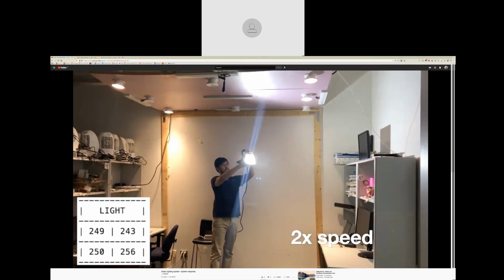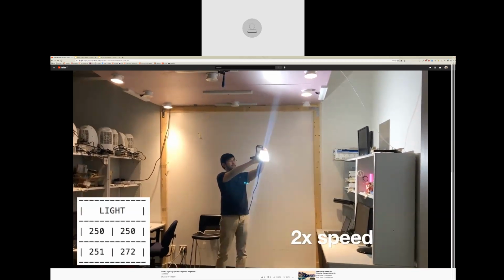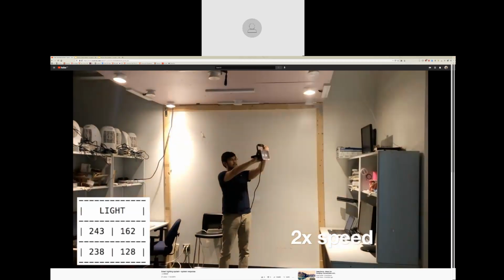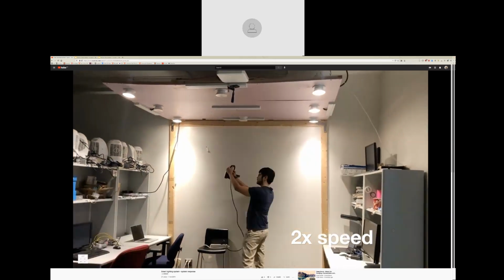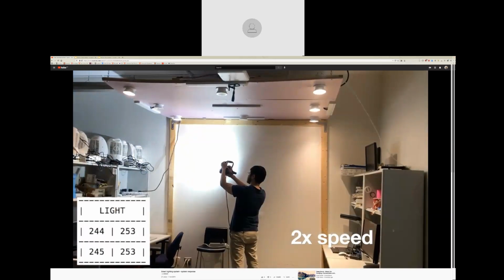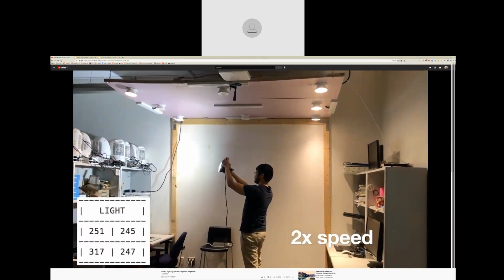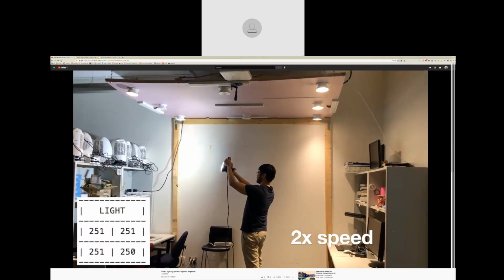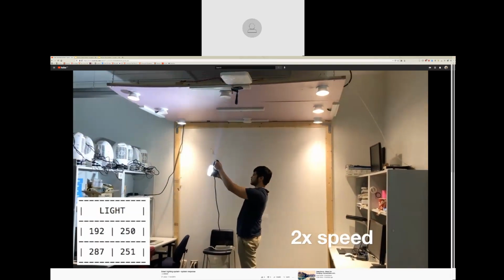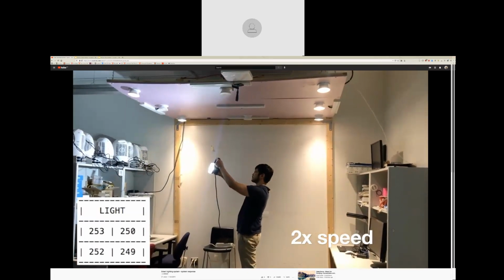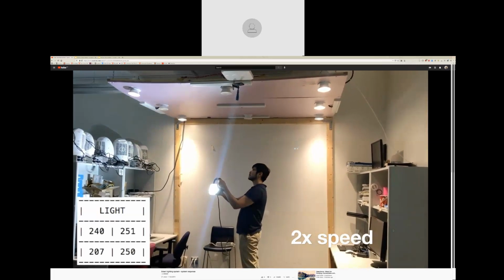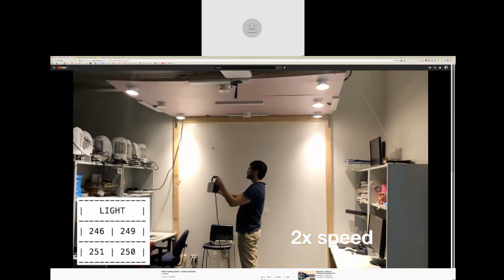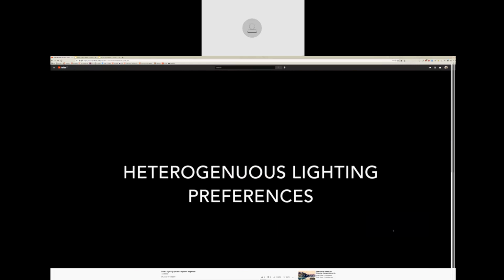And what you see is that we want to have a required level of 250 in this case. As the sun comes out on the lower left, you'll see that it essentially maintains 250 even though the sun is out. So what's happening is the lights are dimming in response to that. The system responds quickly, and we'll measure this. It takes about 1.5 seconds to respond.